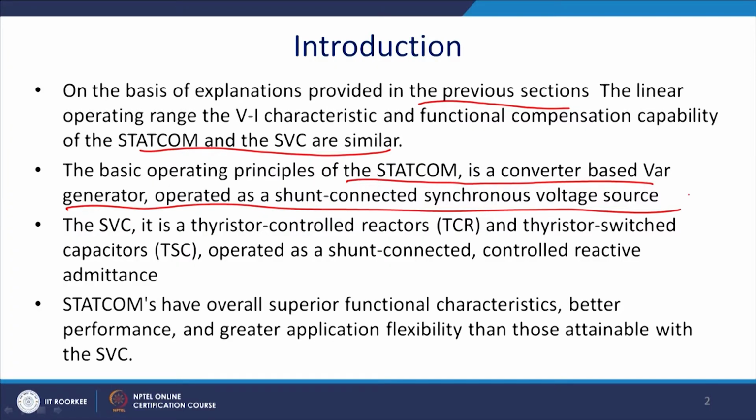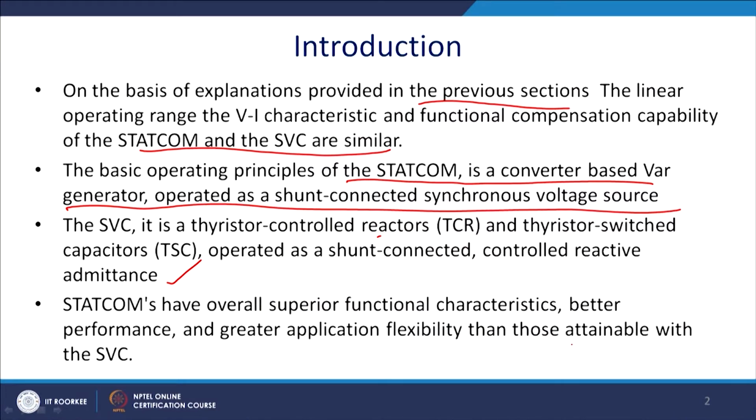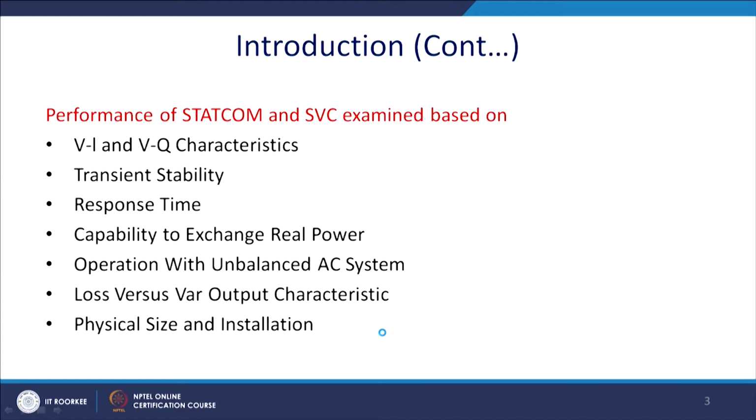SVC is a thyristor controlled reactor, thyristor switched capacitor operated as a shunt connected controlled reactive admittance. So, one is a source, another is an admittance. And thus, STATCOM has overall superior functional characteristics, better performance and greater application flexibility than those attainable with the SVC. We shall establish these consequences with this discussion.